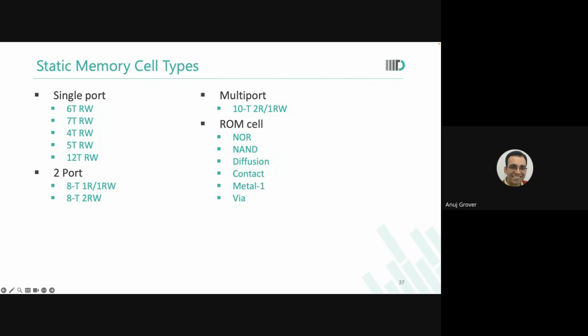Whatever you want to write from port A will be given higher priority over port B. Similarly, you have multi-port memories, where you may have multiple output channels that could be driven by, let us say, one configuration routing control. There are multiple channels and on top of that a routing control. So multi-port memories are used very commonly in routers.